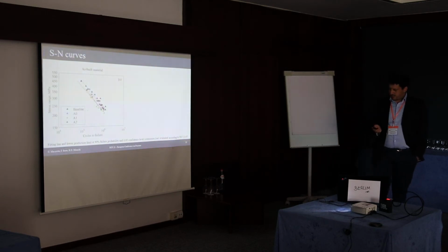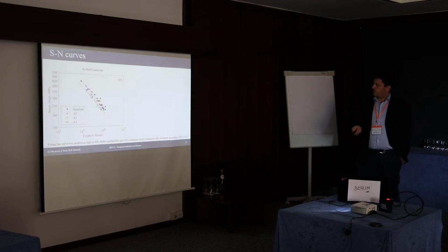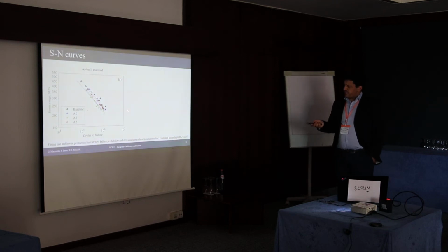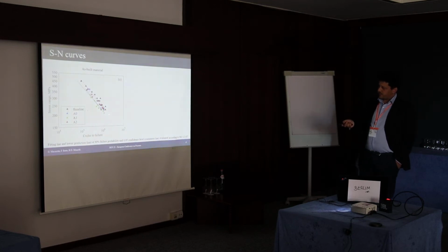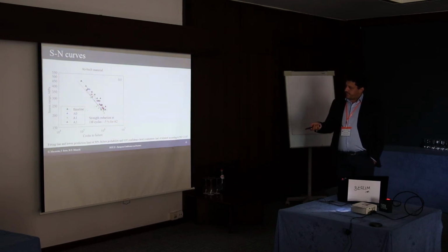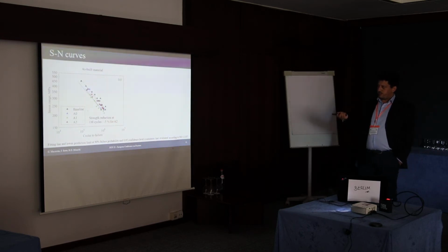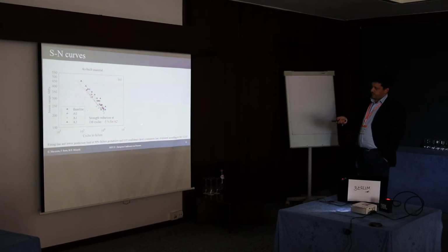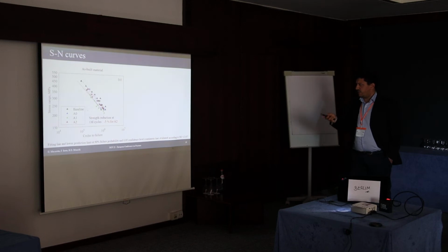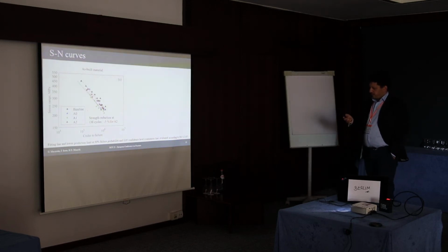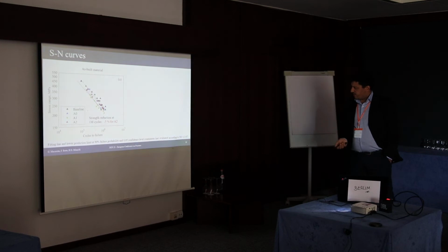If we go to the fatigue test, I'll show you directly all the S-N curves that we tested. You can see that compared to this huge increase in the surface roughness and porosity, the fatigue strength is not reduced so much. If we compare the baseline and the ATU process parameters, that are the two extremes in terms of productivity, we see that ATU produces only a 5% reduction in terms of fatigue strength at 1 million cycles here. The fatigue test was limited only in the part between 10 to the 5 and 10 to the 6 cycles to failure.